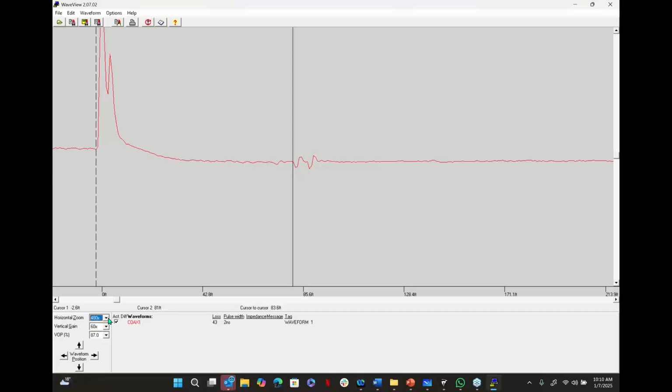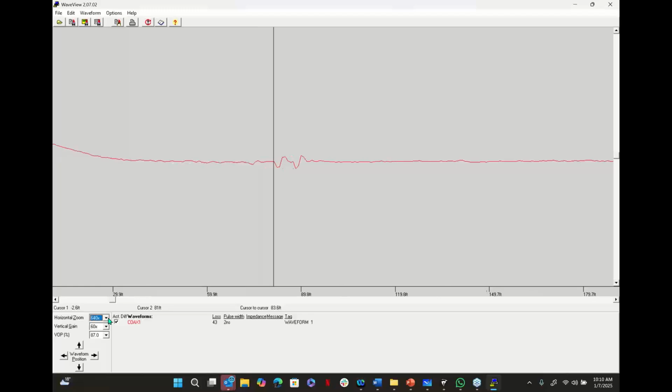From this point, that's a little bit too far, this is as far as I need to go before I can determine clearly this is two separate events. Does everybody see that? I have an S-curve that ends right here and another S-curve that starts and ends right here. The first one is at 84.2 feet. The second one is at 89.8 feet.